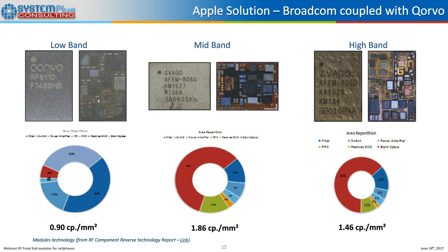All in a SAW filter application, but knowing the performances of its low drift solution, we think that the choice is understandable. With less than 32% of blank space, the solution has a very low form factor. On the mid and high band, Broadcom relies on its F-bar BAW filter and microcap packaging technology.